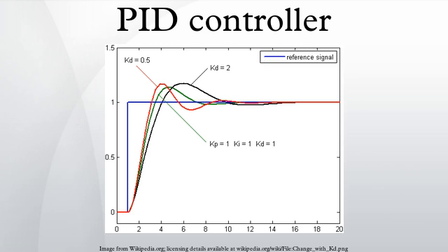Usually, initial designs need to be adjusted repeatedly through computer simulations until the closed-loop system performs or compromises as desired. Some processes have a degree of nonlinearity and so parameters that work well at full load conditions don't work when the process is starting up from no load. This can be corrected by gain scheduling.